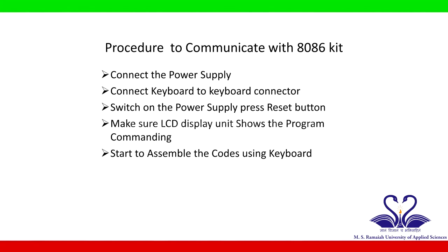Now, let us learn the procedure to communicate with 8086 kit. Connect the power supply. Connect keyboard to keyboard connector. Switch on the power supply, press reset button. Make sure LCD display unit shows the program commanding. Start to assemble the codes using keyboard.